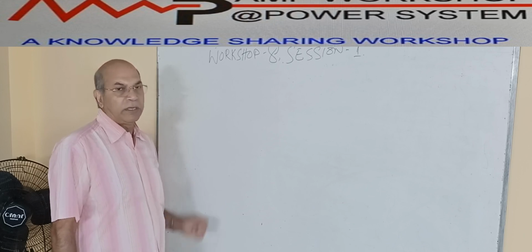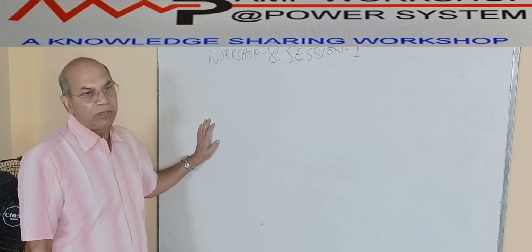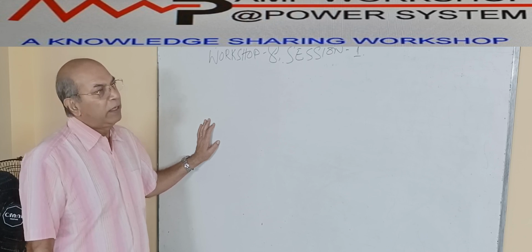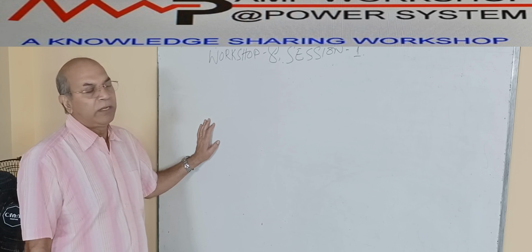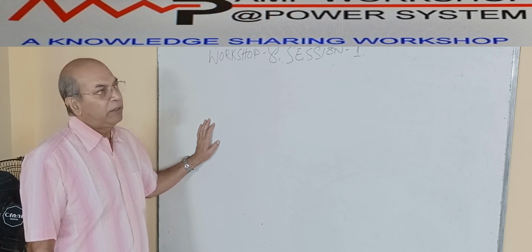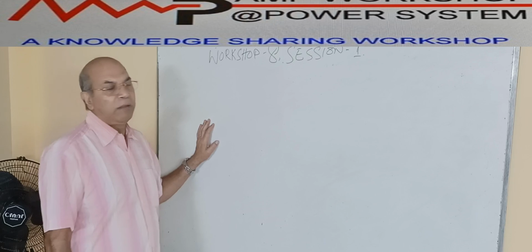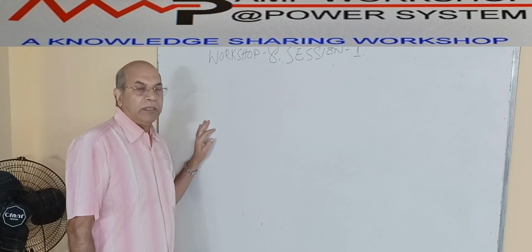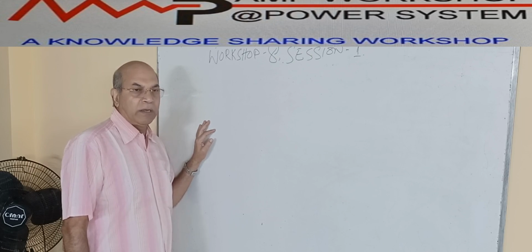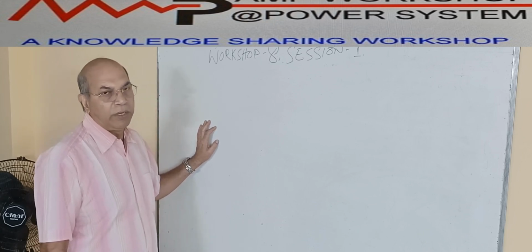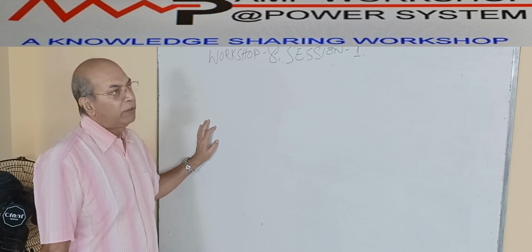There is another way to classify switchgears, by installation location. Whether the switchgears are installed inside a building, meaning indoor installation, or outdoor installation. Generally nowadays, up to 800 kV switchgear can be installed indoors with a special arrangement, and that is mainly used if the location where the switchgear is to be installed is highly polluted, a highly congested industrial area with a high level of pollution. In that case, installing the switchgear outdoors is not very convenient, so we go for indoor installation.